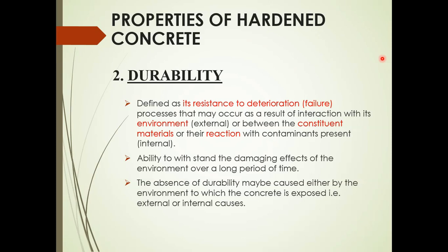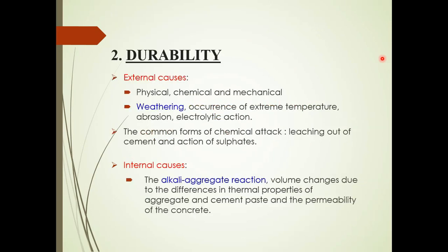The durability of the concrete may be reduced due to some environmental effects. For example, it can be exposed to external effects or internal effects. In durability, we have external causes, which are physical, chemical, or mechanical attack. For example, weathering, extreme temperature, abrasion, and also electrolytic action. The common forms of chemical attack are leaching out of cement and also the action of the sulfates. Okay, so that is for external causes.